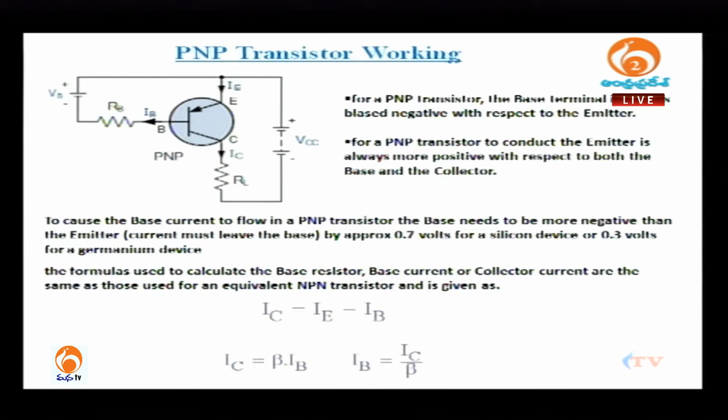This will cause recombination to take place in the base region, and 95 holes or 99 holes are swept into the collector region. This accounts for the collector current. The ratio between collector current and emitter current is called the current transmission ratio or current gain of this particular configuration.